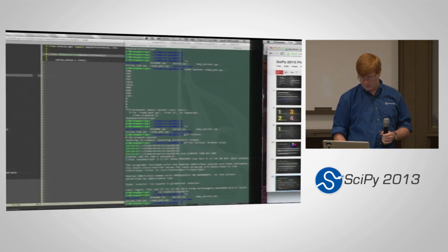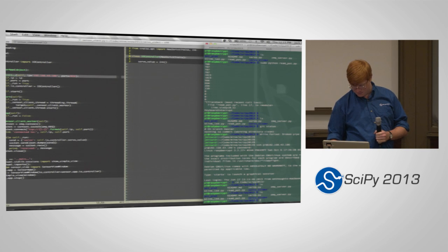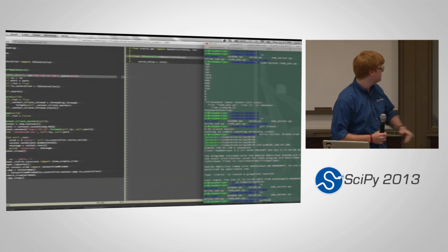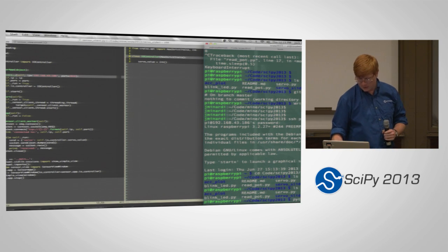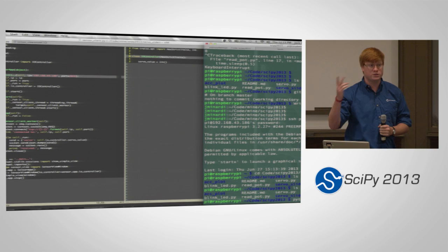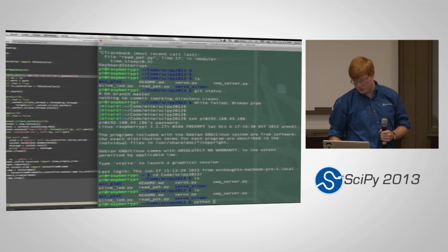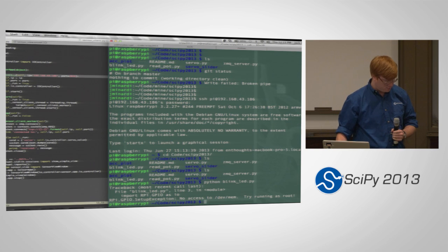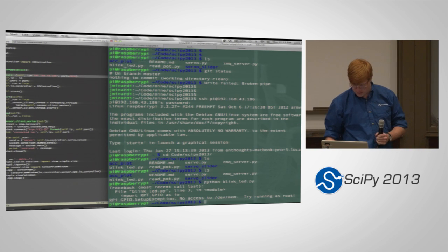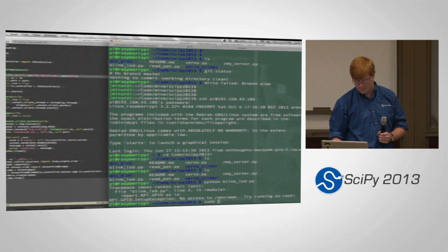And I can demo this if all works out. So here I'm actually SSH'd into the Raspberry Pi. Let's make this a little bit bigger. Raspberry Pis always come pre-installed with Python, so that makes life a lot easier. And I'm just going to run this blink LED script. And you've got to run it as sudo. To have access to the GPIO pins, you need to run as root.